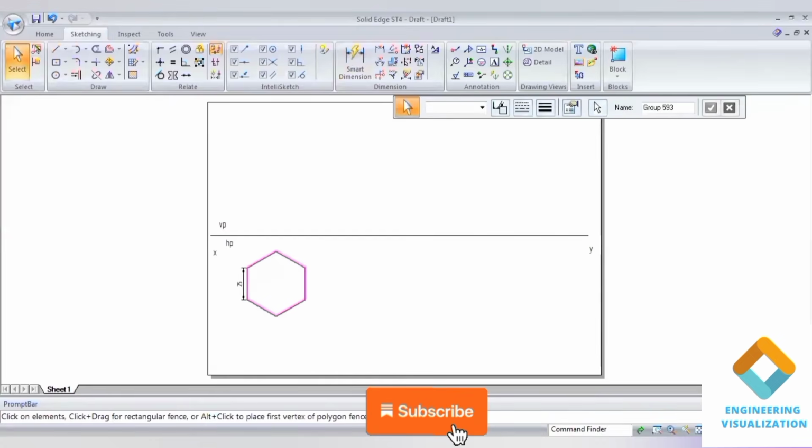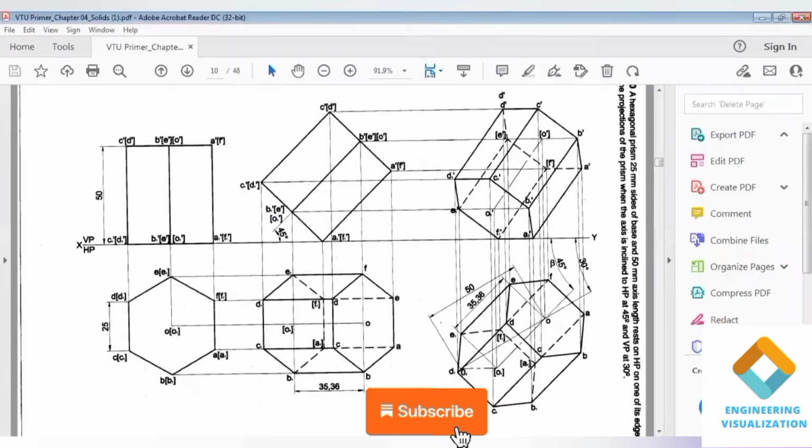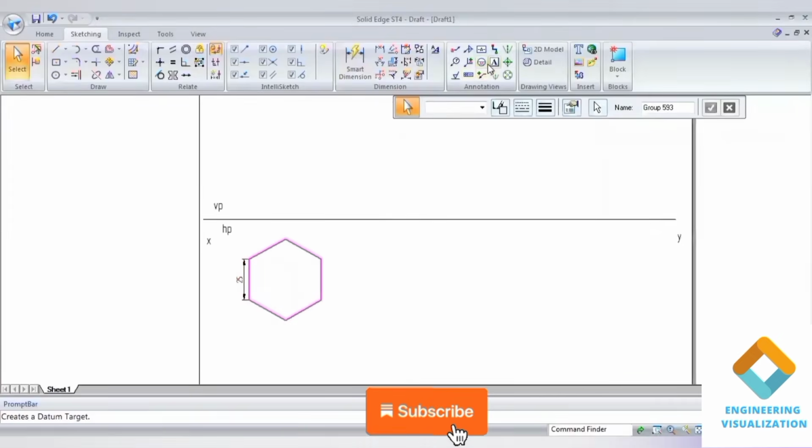Now write the notation, top view and bottom view notations. Top view notations are written with A B C D and bottom face notations are written A1 B1 C1 like that, but it should be written within brackets.